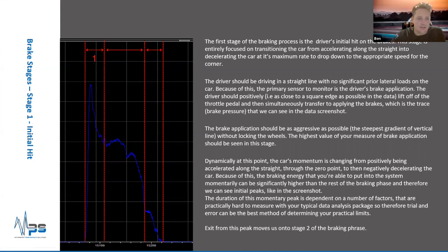which we can utilize. We can gain extra performance if we utilize all of it when the driver applies the brake. Again, using the 80-20 rule, the width of this is very hard to calculate dynamically. There's a huge amount of complex factors which are always changing. Track conditions change, brake conditions change, tire conditions change, etc. So it's very hard to say you need to get up to 98.2 here, or otherwise you're not maximizing your braking performance.